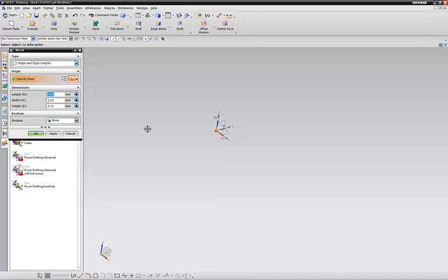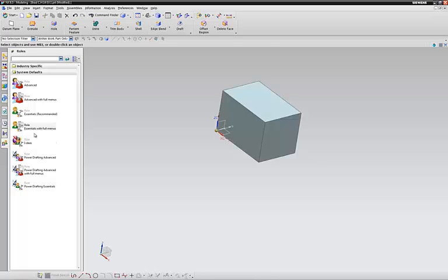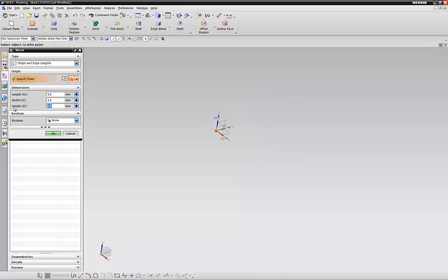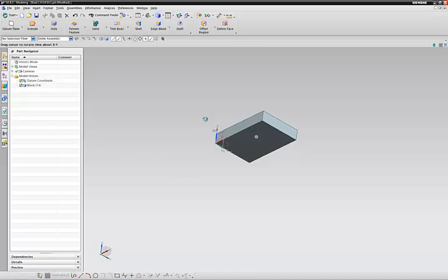So our part is 96 in the X direction, and it is 64 in the Y, and in the Z direction 64. It is, but that's not what we wanted, because I don't want to be cutting out this block. We only want to make it go up 12, or no, 16, for that's the height of the bottom piece. There, that looks a lot better.